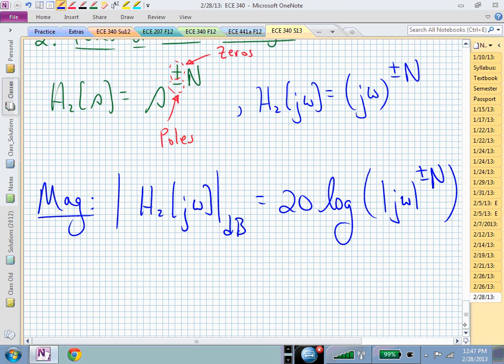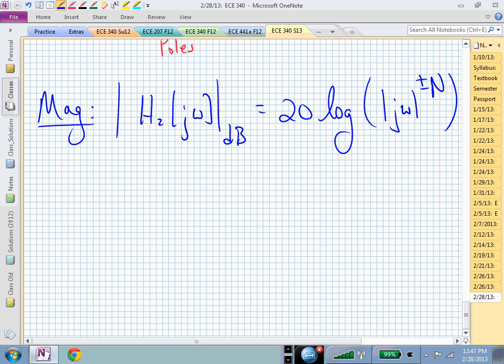And the other thing that's nice is since we're dealing in dB and taking the logarithm of this argument, now when we have the argument containing exponents, that exponent flies out in front. And now we can have plus and minus 20 capital N log of omega. And that's exactly the same expression, meaning we can now say that this magnitude looks like that. And again, this is a logarithm base 10.